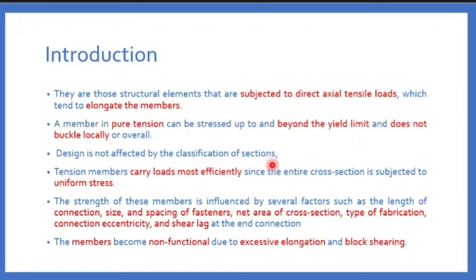In design of compression member, while starting I have discussed with you the types of section. So what are the sections for the steel structure? Plastic section, semi-compact section, compact section. These three are the types of section which are there in your code book also. You have a tabular column, you will be selecting breadth to thickness value in order to find that.